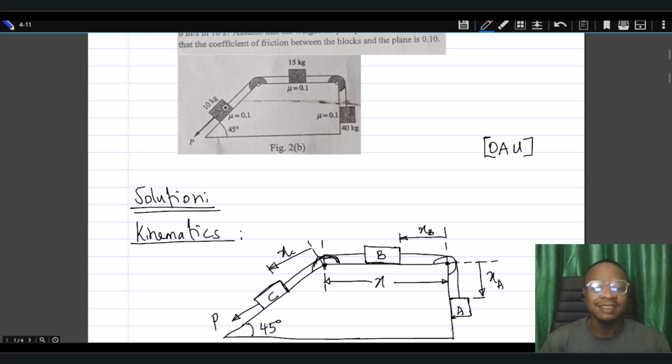In this case, there is also the weight, but the weight is not directly perpendicular to the surface. So we'll get some components of the force that are perpendicular to the surface. That is what directly presses this body against this surface, and that is what will determine what the normal reaction from this surface will be.